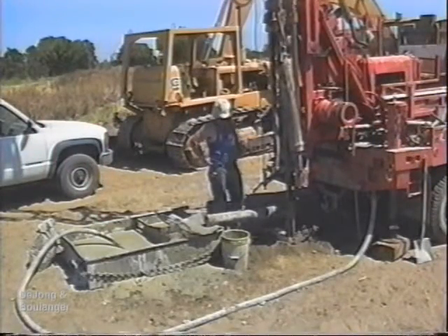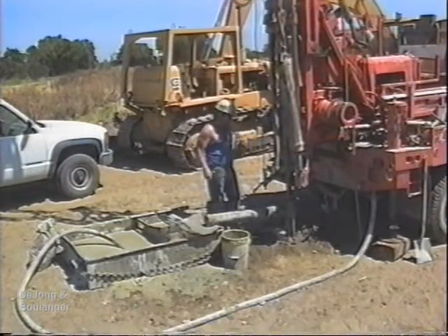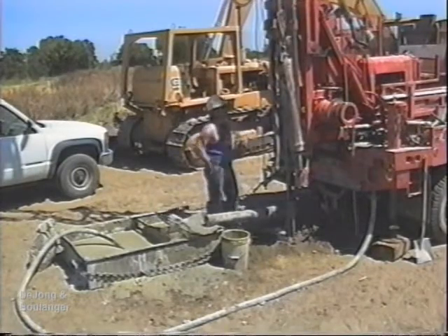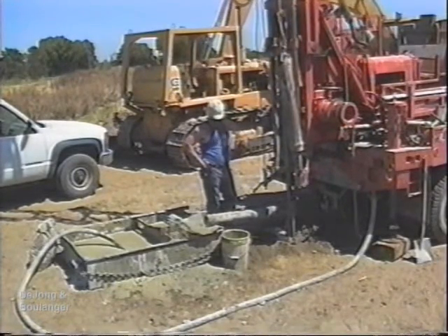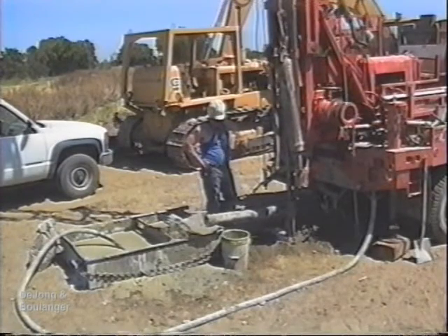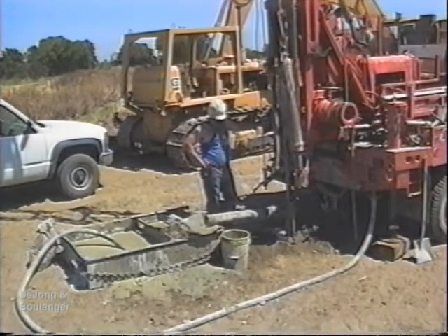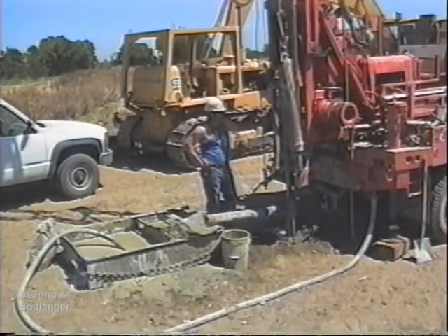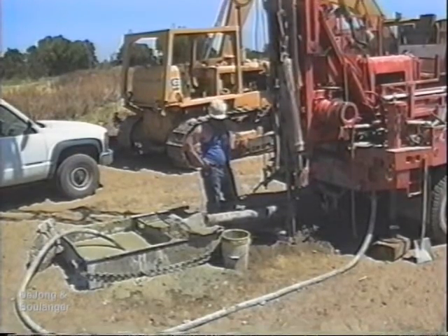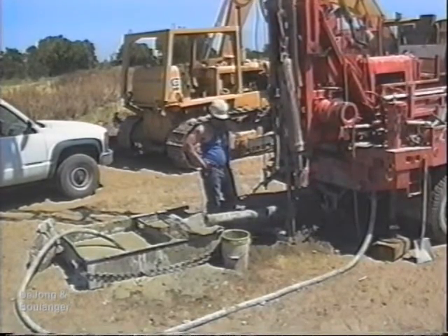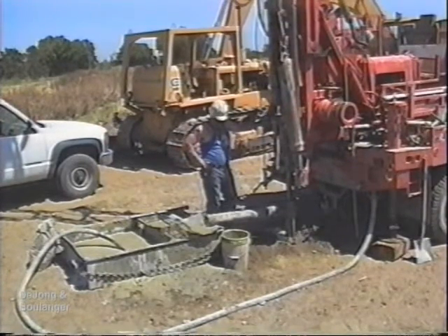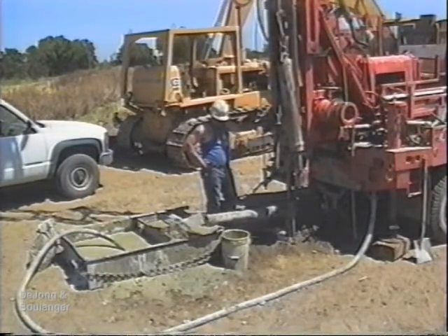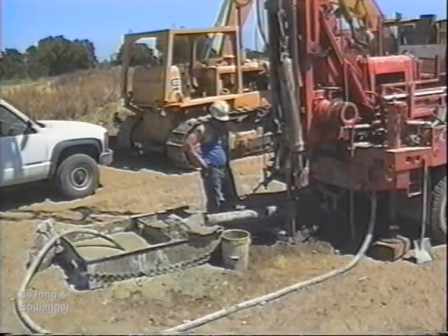Mud rotary drilling is preferred over hollow stem augering. If hollow stem augering is used, the hollow stem must be continually filled with water or drilling fluid to an elevation above the surrounding water table. Otherwise, inward seepage of water at the bottom of the hole could loosen the soil, thereby causing N values to be unrepresentatively low. This inward seepage could also erode soil into the auger stem, which, if mistaken for the bottom of the hole, could cause N values to be unrepresentatively high.